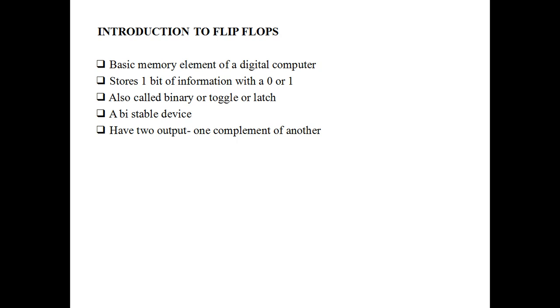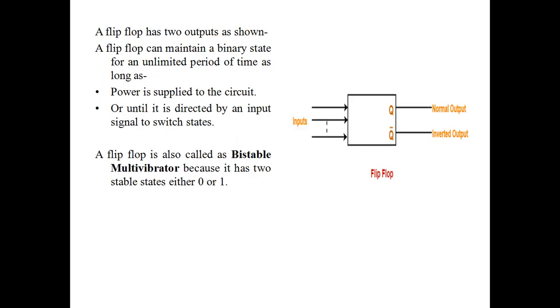Flip-flops are used as data storage elements. It is the basic storage element in sequential logic. A flip-flop is a device which stores a single bit of data. One of its two states represents a 1 and the other state represents a 0. Typically, a flip-flop includes 1 or 2 inputs, as well as a clock signal as input, and an output signal. Some flip-flops also include a clear input to reset the current output.